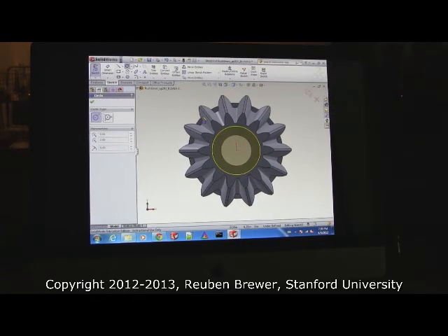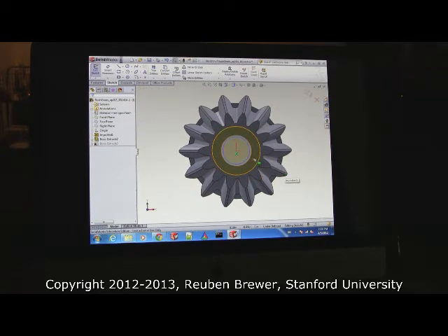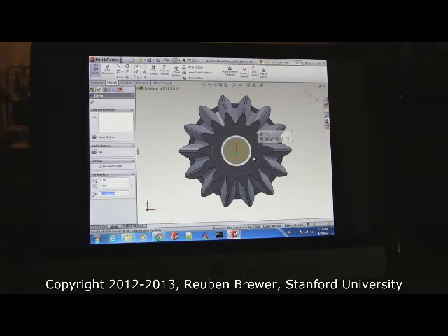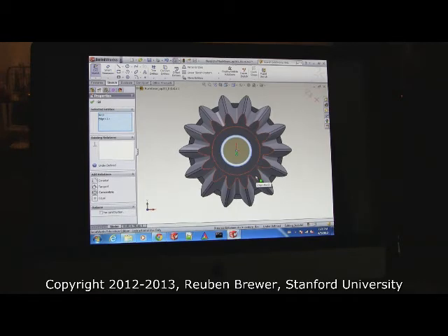Is everyone in this sketch view where I am right now, sans the yellow? Select a circle, put it in the middle, drag it to about here. Press escape. Now select the blue circle, hit Control, and hit the circle next to it that already exists. Your screen should look like mine. If you've already got it, you can leave it. I'm redoing it because some people didn't get it.